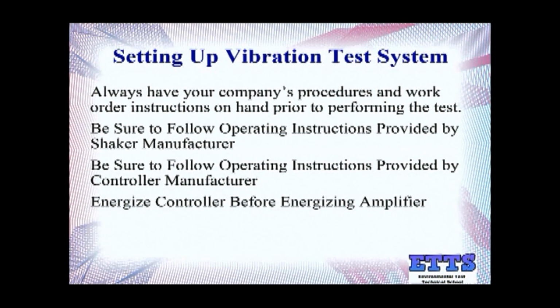Be sure to energize your controller before energizing your amplifier. The reason for this is you could possibly send a transient signal through your drive cable into your shaker system when powering up the vibe controller. This could damage your shaker and/or your unit. So don't ever power up your amplifier or your shaker and then energize your controller. Have your controller energized prior to powering up your amplifier.